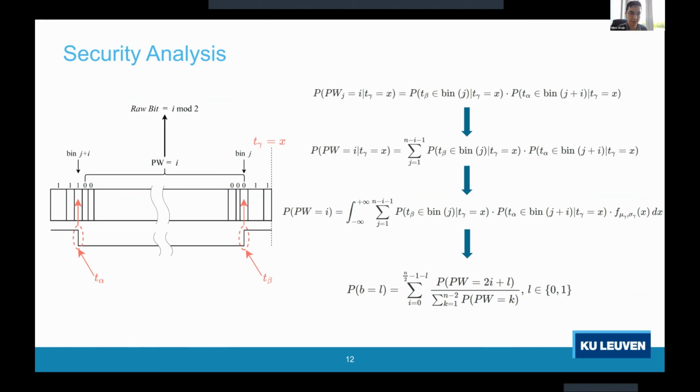So this result will only be output when there is a string of zeros encircled by ones from the left and the right side. And then we XOR them all together and we obtain one number, because as I said, the bubbles will be detected by the XOR. So you XOR them together. That's a simple way. Yeah.